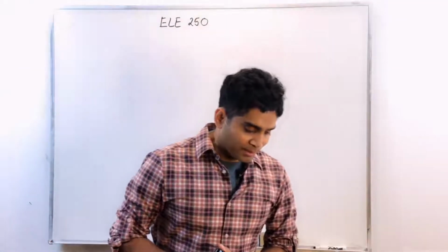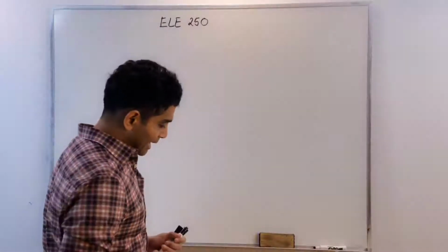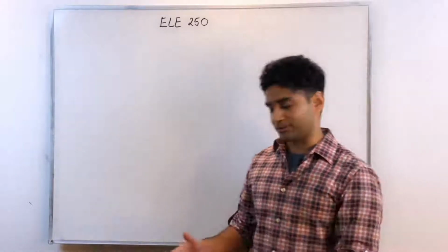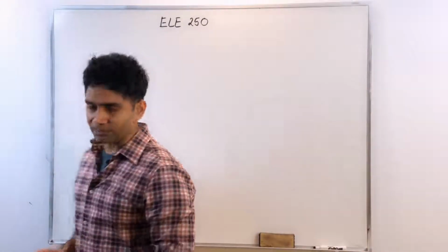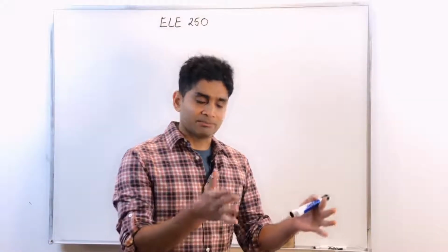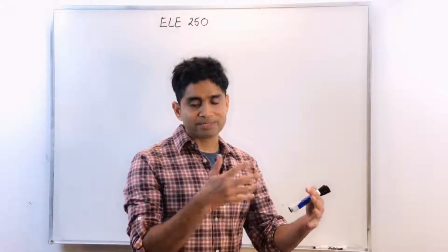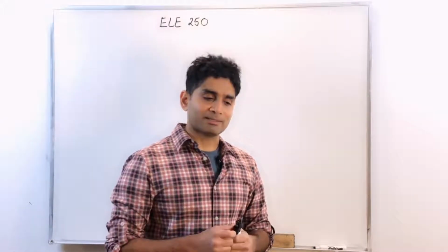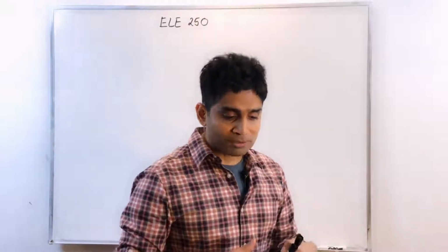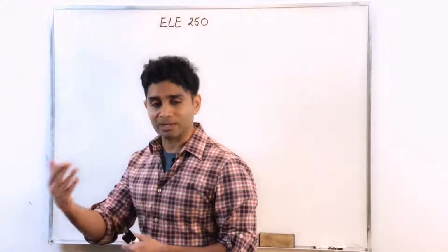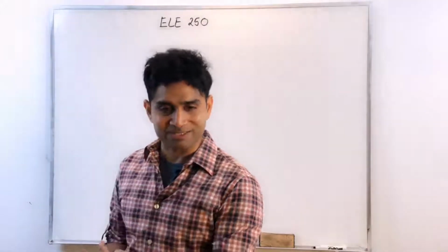Now, just to give a quick recap of what we did in the last class, we looked at the D flip-flop and some applications of it. We looked at the register, the parallel load register, and how these registers are interfaced with the data bus, and also another alternate way of implementing registers. We also have the serial version of the registers called shift registers.